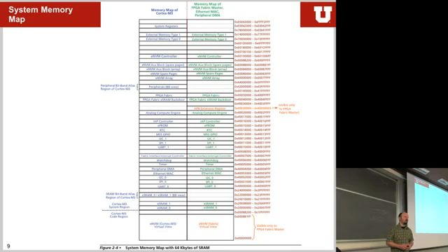Last time we talked about memory. Today I got a question that I'm not entirely sure is the answer, but sometimes you can address the individual bits of a register sitting in memory by using one of the words. And that's in these locations here. If you have an address in the peripheral bitband alias, these aliases point to memory locations in the peripheral section. So the peripheral sections are all down here. This is the bitband area for it.